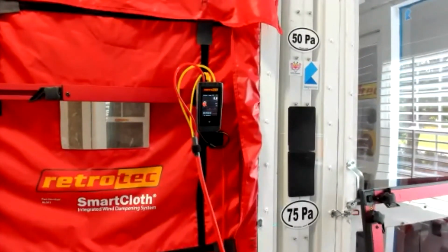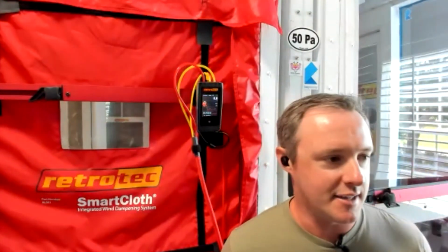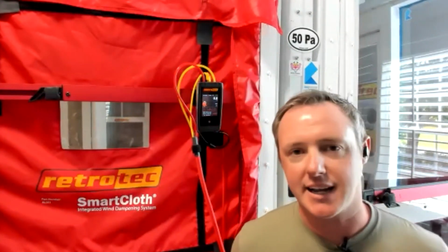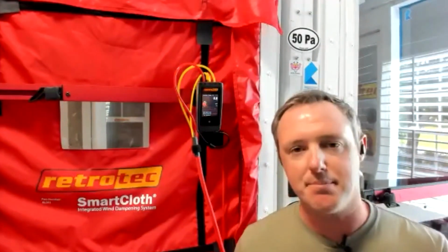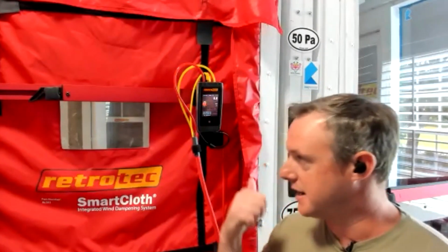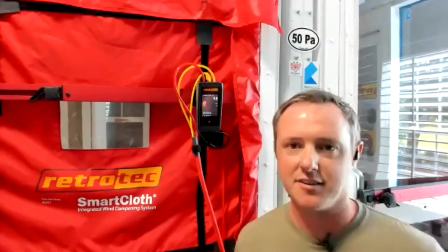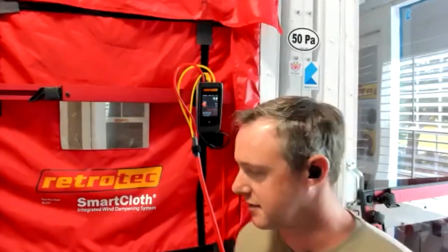Then we're ready. So the first thing that we want to do is what's called a baseline. I talked about wind earlier. Any kind of activity that is happening to the house, like wind or stack effects, we don't want to count that in the equation when we run our blower door test. So we do what's called a baseline reading. We let the gauge read the outside conditions for a little while, and any differences between inside and outside, it'll remove that from the equation. So let me show you what that looks like.